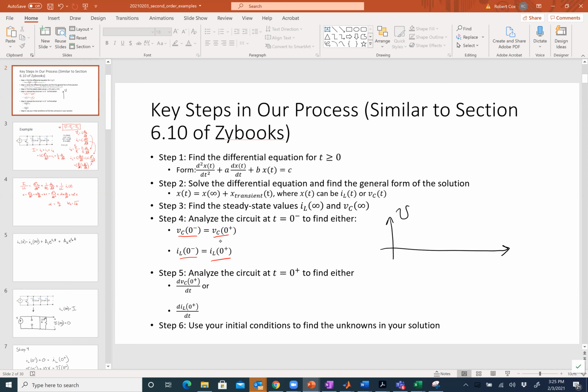If you go back to the first lecture on this, I did sort of an example where I looked at a simulation, but the capacitor voltage has to be smooth and continuous. It could never just suddenly go like this. I couldn't have a discontinuity, is what you would call that in math. And I can't have a discontinuity because the physics just say it's not possible. Okay.